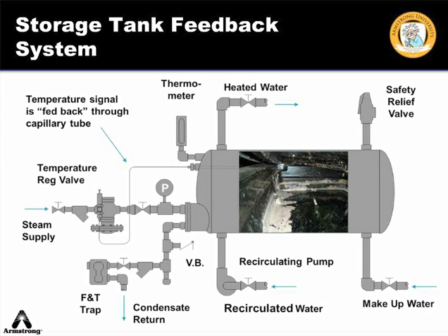Food sources such as algae and amoeba come in from the city water supply. Silt and other materials in suspension within the water also come in with the city water. The bottom of these tanks provide the ideal conditions in which Legionella likes to colonize, including the right temperatures, stagnant conditions, and a food source.